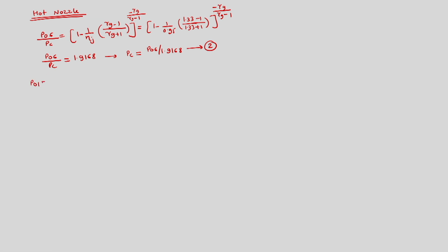Here we know P01 is 1 bar, then we know P02 is 1.65 bar, then we know there is the combustion chamber, there is P03 which is P02 risen to P03 in the compressor. So P03 was 22.98 bar, which is based upon the pressure ratio of the compressor. Then there is loss in the total pressure, which is 1.5 bar, so it is 21.48 bar.